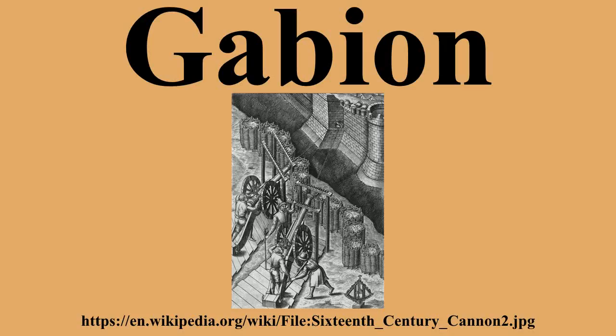Gabions also have advantages over more rigid structures because they can conform to subsidence, dissipate energy from flowing water, and drain freely. The strength and effectiveness may increase with time in some cases, as silt and vegetation fill the interstitial voids and reinforce the structure. They are sometimes used to prevent falling stones from a cut cliff endangering traffic on a thoroughfare.